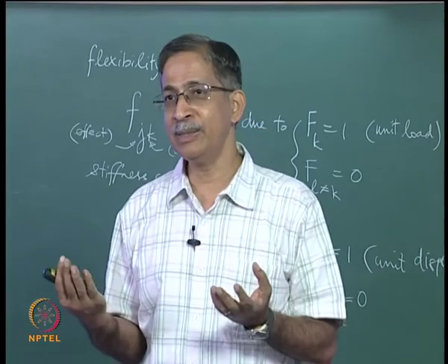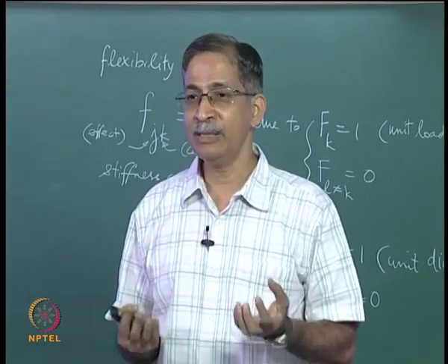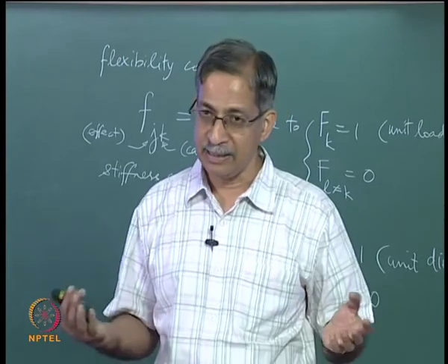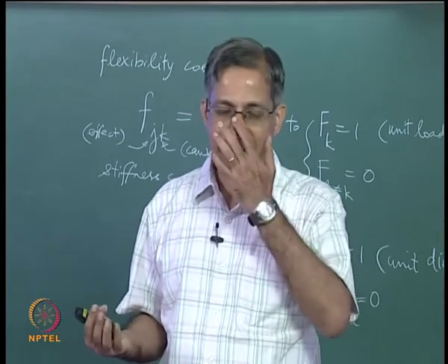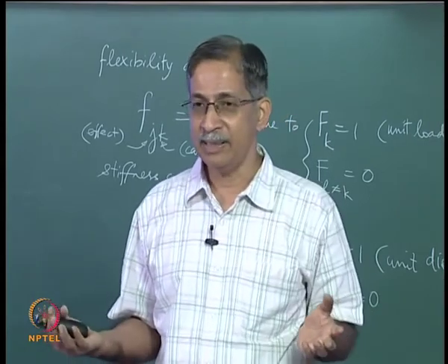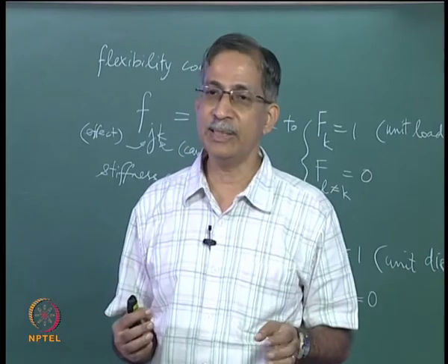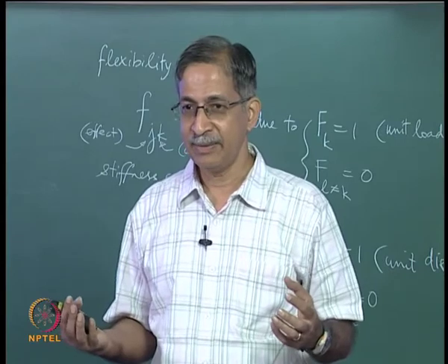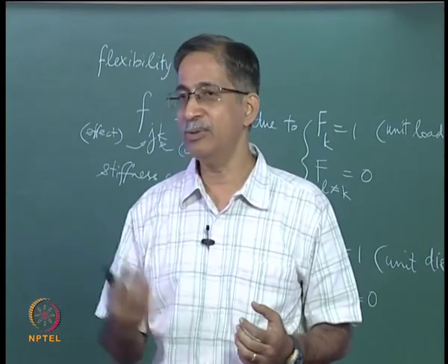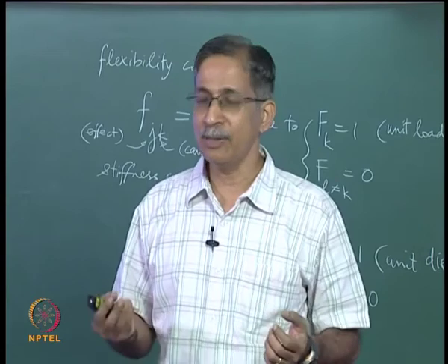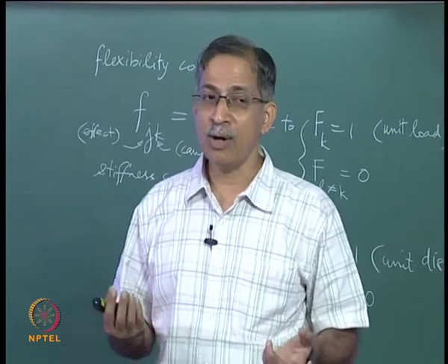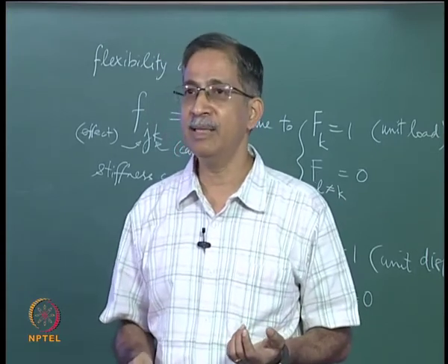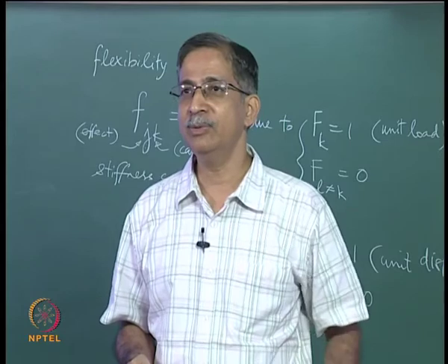You might ask, why should we struggle and do all this? Why do you need to use kinematics to find a static solution? Can't we do it directly? Yes, you can. If the system is statically determinate, you can directly invoke equilibrium, but you will find there are some situations, for example situations where you have multiple internal hinges, you will find it is much easier to invoke this principle. It is also called the dummy displacement method, but you could call it the unit displacement method, like the unit load method, when you put that dummy value equal to 1.